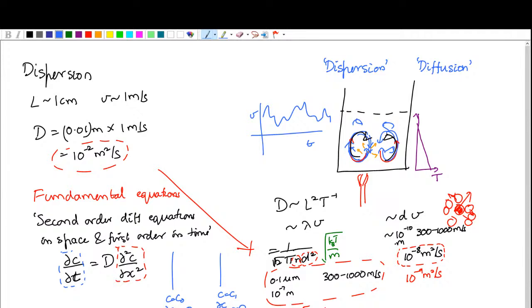And finally, if a PFR with a very high recycle ratio is considered, how does it affect the boundary conditions used? The recycle ratio does not affect the boundary conditions because the boundary conditions are determined only by the interaction of the fluid with the boundaries. Okay? So, regardless of the recycle ratio, at the walls of a PFR, if I take that as some kind of a pipe or something, the boundary condition at the wall for the mass will be that there should be no flux across, because the boundary is an impenetrable medium, so there should be no flux going across the surface.